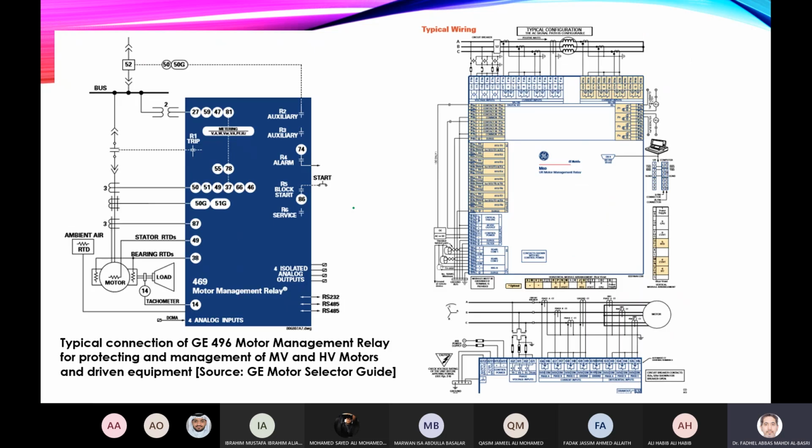This is another slide that shows that for medium voltage and high voltage motors, you need additional protection. You may need RTDs, temperature sensors on the bearings, in addition on the motors. Sometimes you need to measure the ambient temperature, the intake. I can measure the stator winding RTDs.